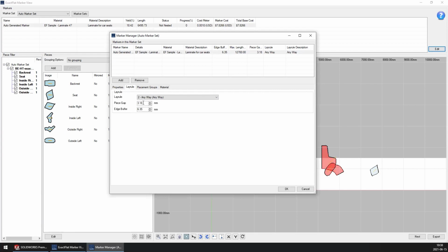So typically in a cutting system type, your cutting table operator is going to specify an overcut just to make sure that the pattern pieces are really good and cut out of the material. For tools like a blade cutter, like a wheel cutter, you typically need overcut just because of the way the cutting implement works. Wheel cutters go around corners nicely, but they need additional overcut to make sure that they fully cut all the way through the material, whereas a drag blade is very good for precise cuts, but they don't turn corners well.